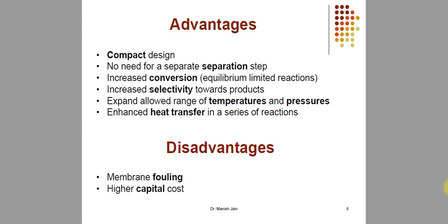Now the advantages of membrane reactors. First is the compact design. Otherwise you would have to use different chambers: one chamber for separation, one for reaction, then another chamber again for separation. Here you have a compact design where the separation and the reaction occur in a single chamber, inside a reactor only. No separate separation step is needed.